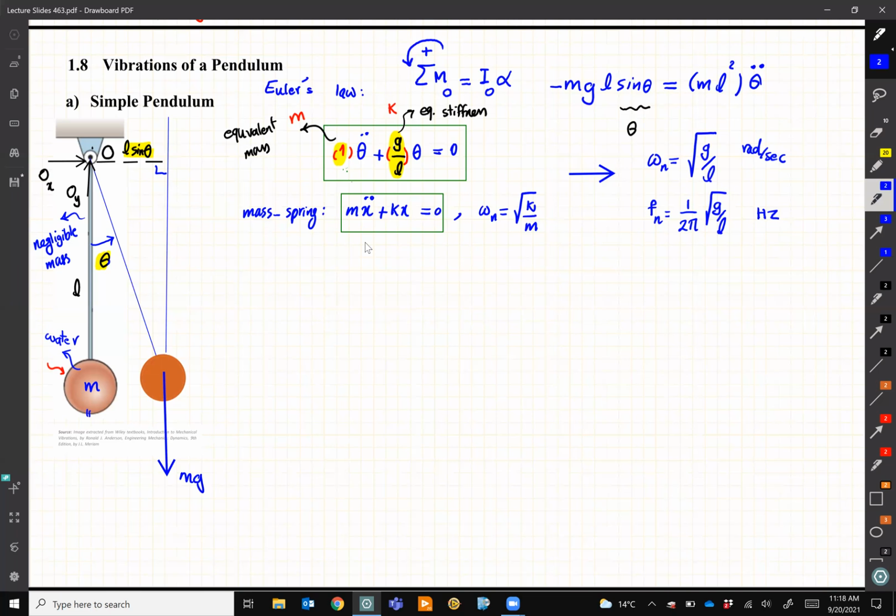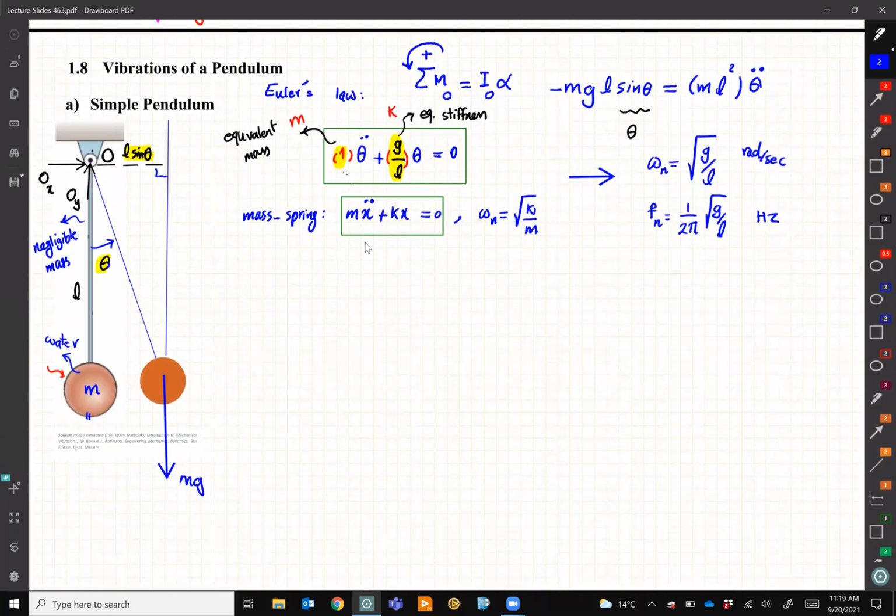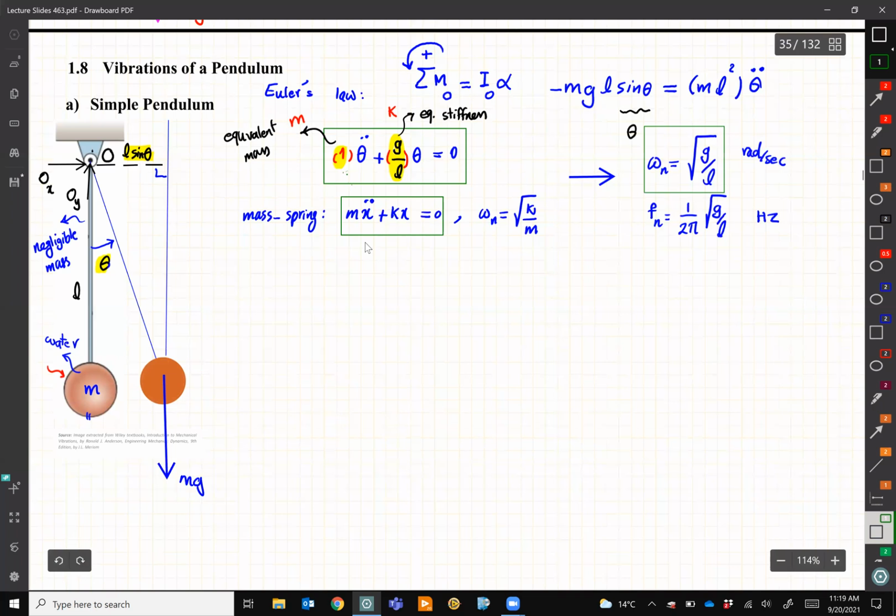And then this thing swings, vibrates. Is the natural frequency of this system going to stay the same over time, or is it going to change? That's the question I was asked. Is it clear? So the system is the pendulum, the water is dripping, right? Slowly. And over time, we are interested to know if the natural frequency of this system is going to stay the same or is going to change. And here is the formula, everything that you learned in your vibration course, that the natural frequency is square root of g over L.